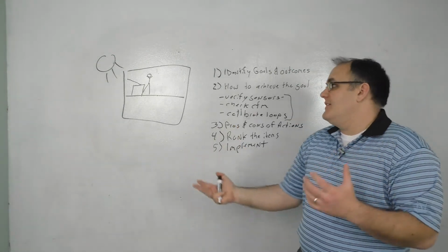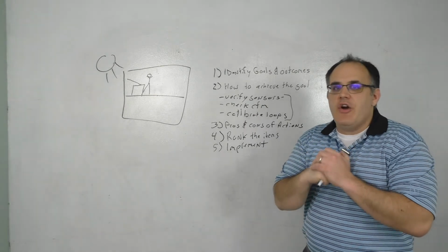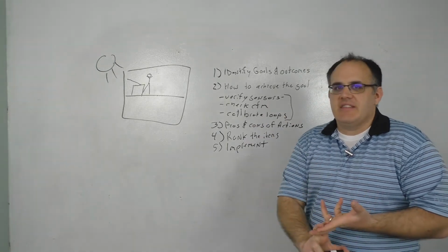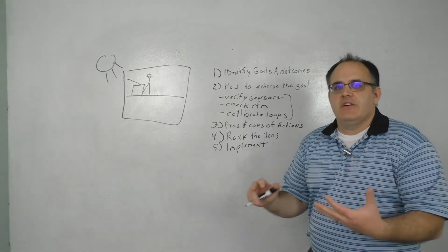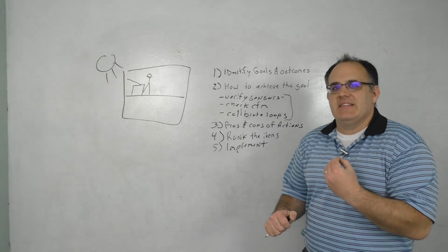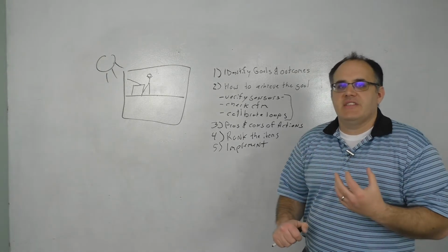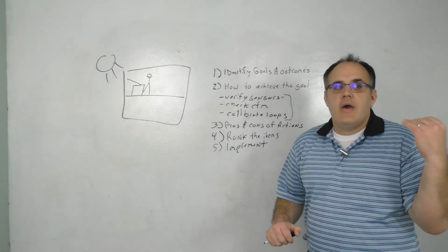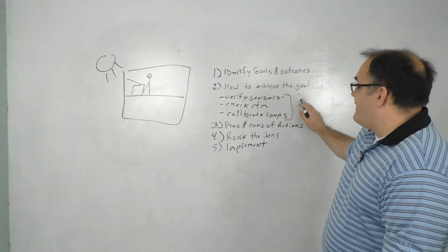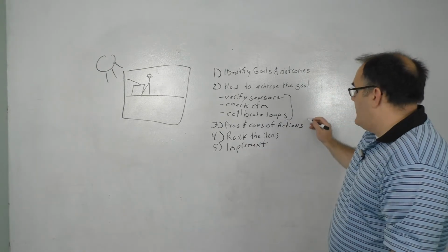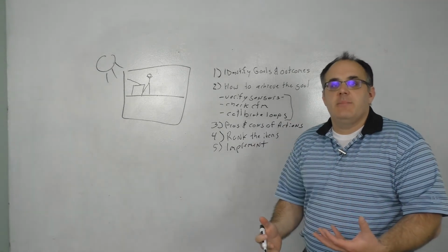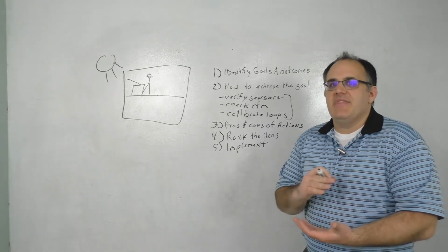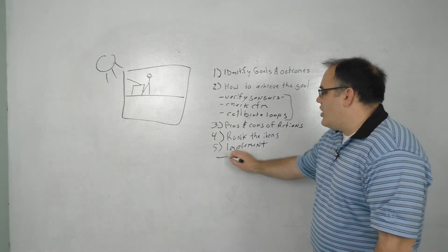I know for a fact that it's the sensors that are bad. So if we just go fix the sensors, you'll have temperature control. You go fix the sensors, no one checked the CFM, no one checked the dampers, no one checked the air handlers, and you still got problems. This is why you need to avoid the tendency to listen to the loudest voice in the room. You need to go, and I know this sounds like I'm contradicting myself when I'm saying go and do step 2, which is identify how you're going to achieve the goal. You should still, before you implement, go and get feedback on the ideas you've come up with. Validate that they indeed address the problem. And then, and only then, do you go and implement.